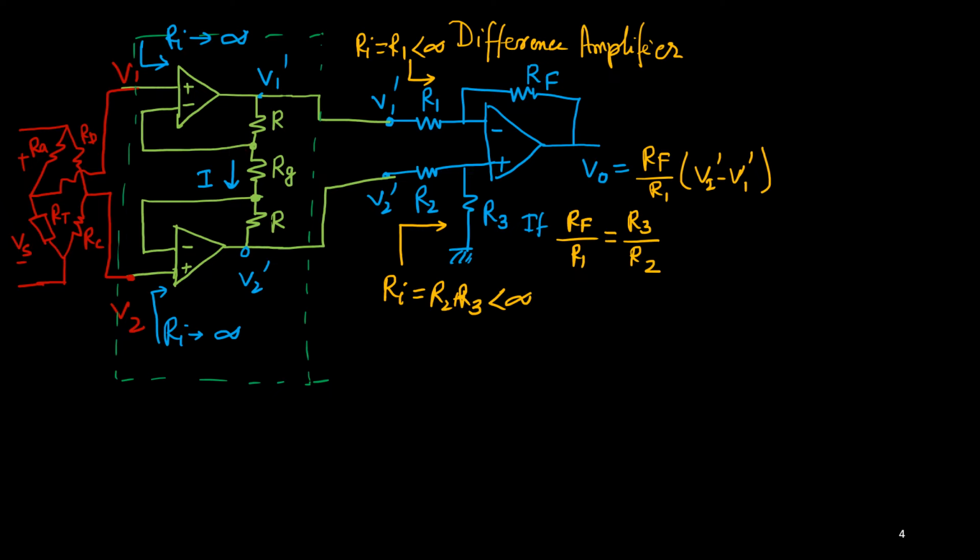So this potential I can consider V1, and this potential I can consider V2, because again there is one negative feedback. So this circuit is having negative feedback by this element R. So these two ends are virtually connected. So this potential is V2. So this potential is also V2. So what is the current I?